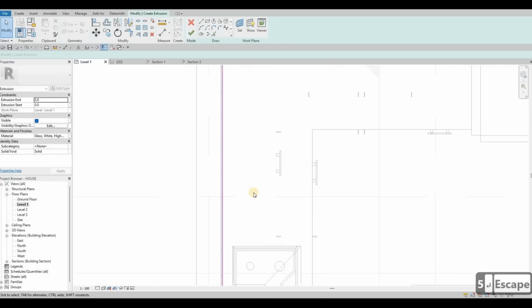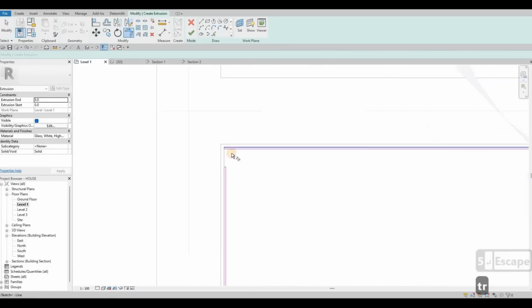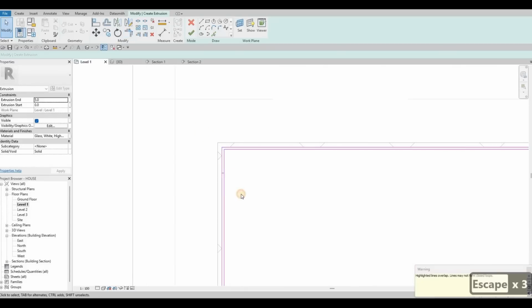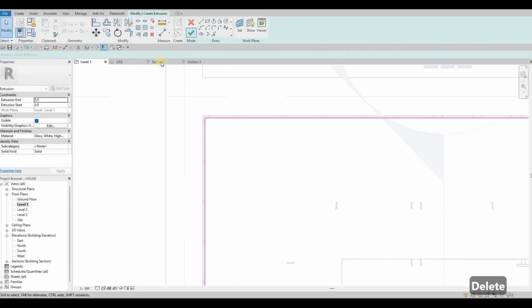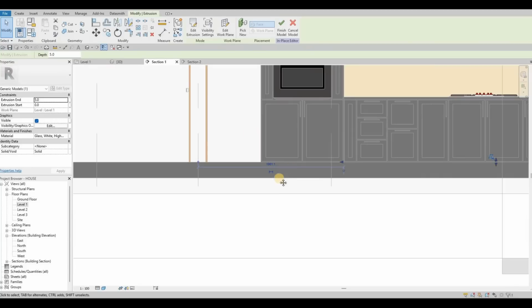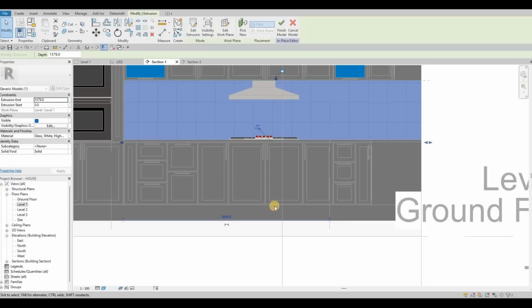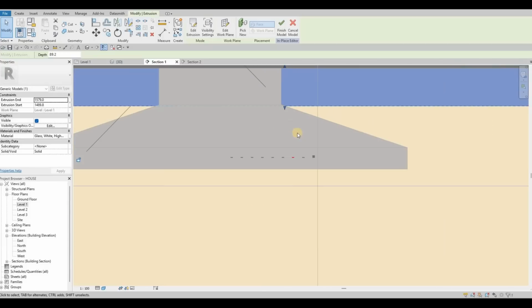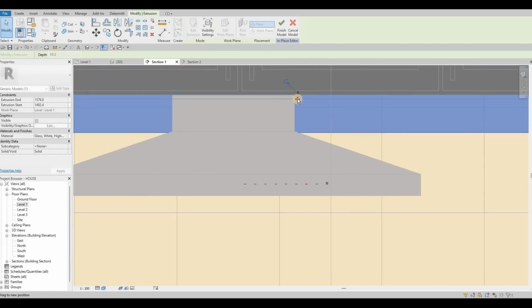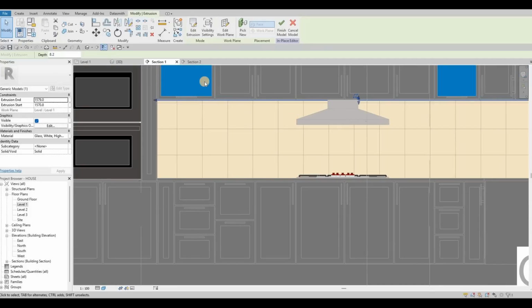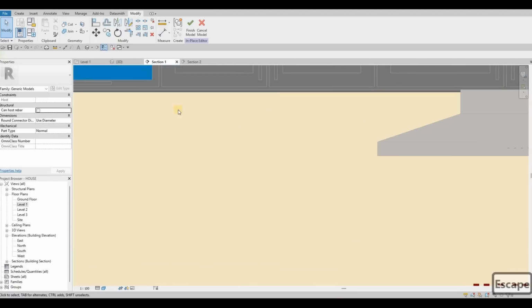And then let's click TR, trim index, and then delete those small lines there, and then click finish. And then I want to see it in right here, but we're going to pull it up to this top. And then once we're in Twinmotion, we're going to choose materials that will light it up. So something like that. That will be perfect for our lights.